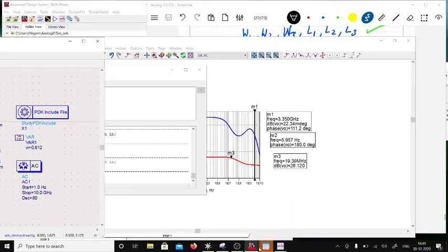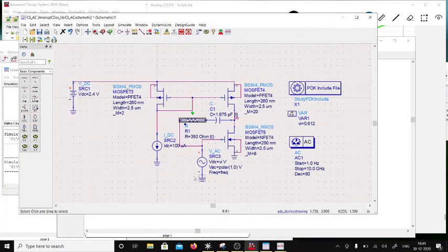And what's the problem? The problem is the input voltage range is too little. It's hardly 60 millivolts. And then the swing is restricted by the overdrives, right? So these problems can be overcome in other circuits which will come up. Now, this is a common source amplifier. So I am going to stop here. A common gate and common drain are much easier, which I'll do in the next session. But for this session, I'm going to stop.